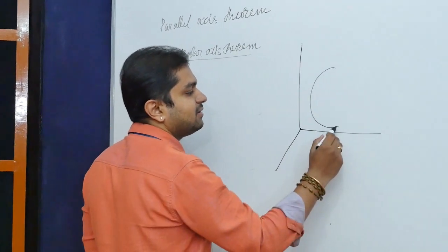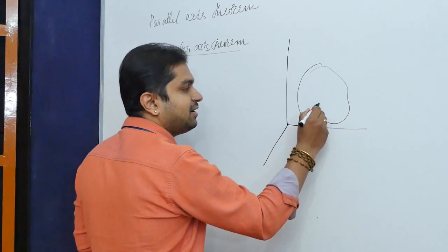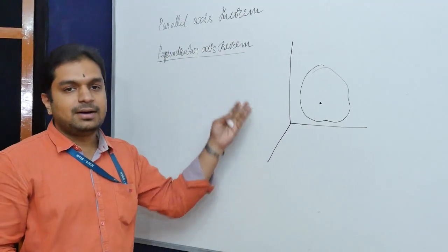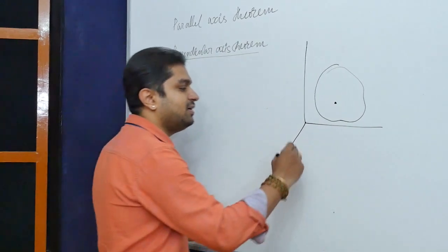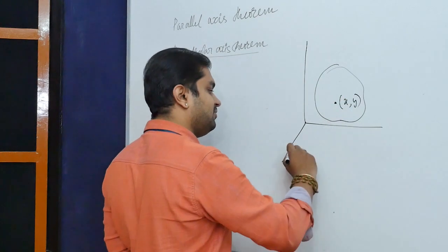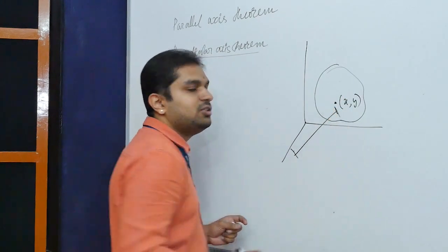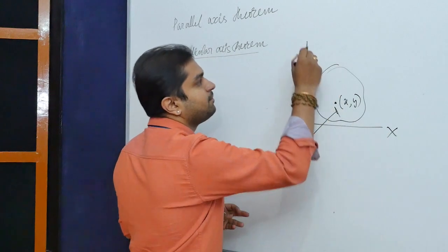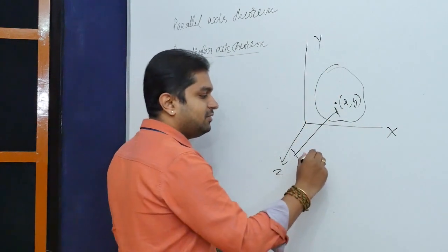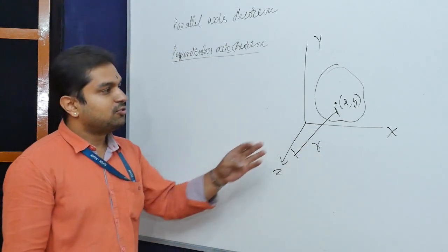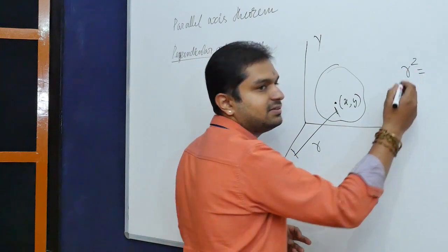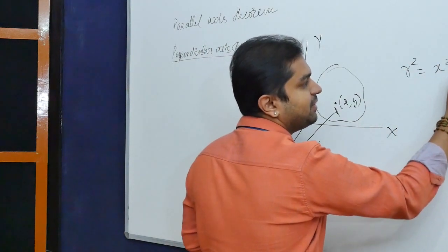We know that the moment of inertia is the area multiplied by the distance squared. If x and y are the coordinates of the distance, and we find the moment of inertia about an axis perpendicular to the plane of the board, the z direction, the distance is marked here as r. From the Pythagoras theorem, r squared, the hypotenuse, will be equal to x squared plus y squared.